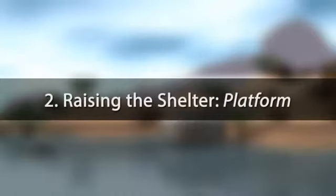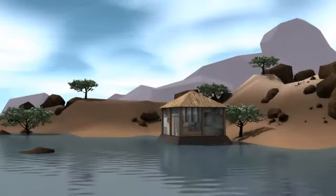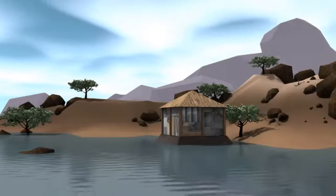Second tip: raising the shelter. Building a platform. Another option is to raise the shelter on an earth platform. It is advisable to compact the earth, stabilizing it with a small portion of cement if possible, and build the shelter on top of this platform.